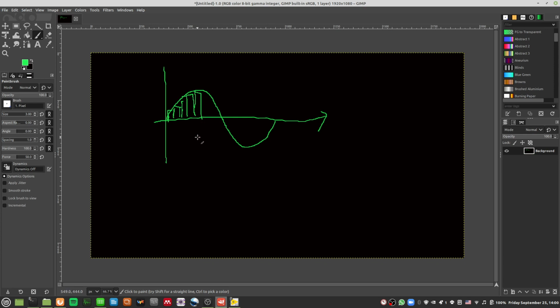It's your sampling, your discrete time signal of your audio file. They will have this sampling interval, they will have this dt. So every time you pass that much dt, it will take a sample, and you pass dt again, it will take another sample. So that's basically what the whole sampling process is like.